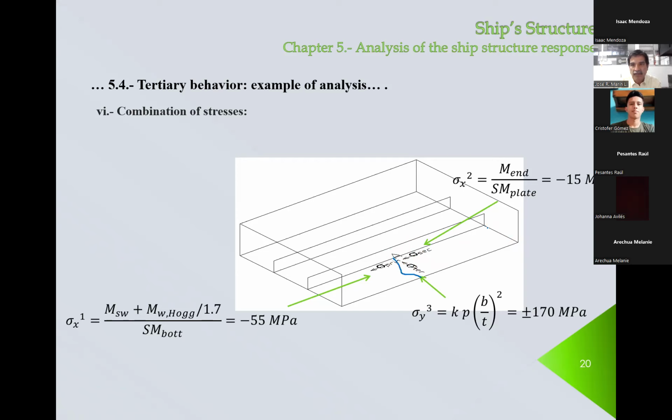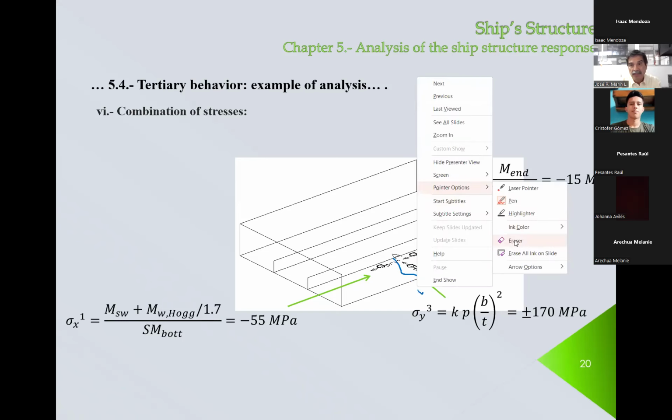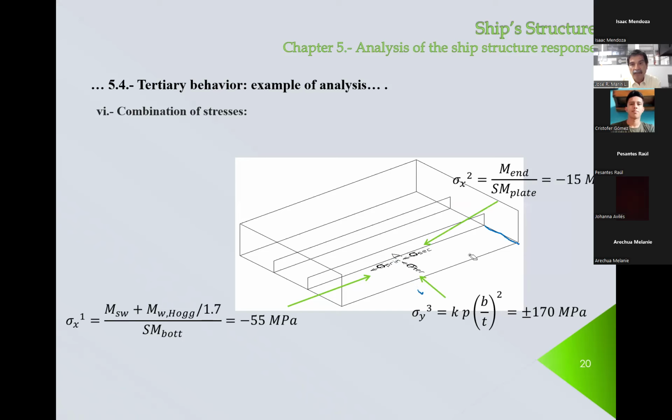The deflection here is going to be like this. So here, the bending moment is going to be larger than in here. So that's why we selected this point. Now, in these cases, when you have to do this analysis, the typical situation is that you try to do this analysis in several points, just to check that your intuition makes some sense.